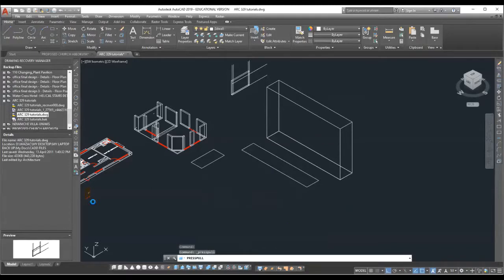Sorry, the system is taking time, maybe because the file is heavy. You can see that because this is also a closed polyline, this press and pull command works here. Once I place my cursor inside this place, I can click and also drag it to whatever height I want it to be. I can also come to this edge now of this object.